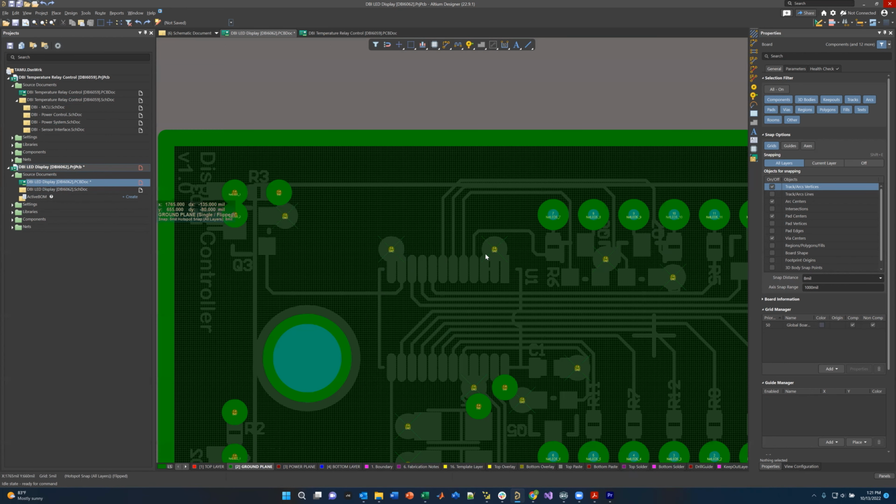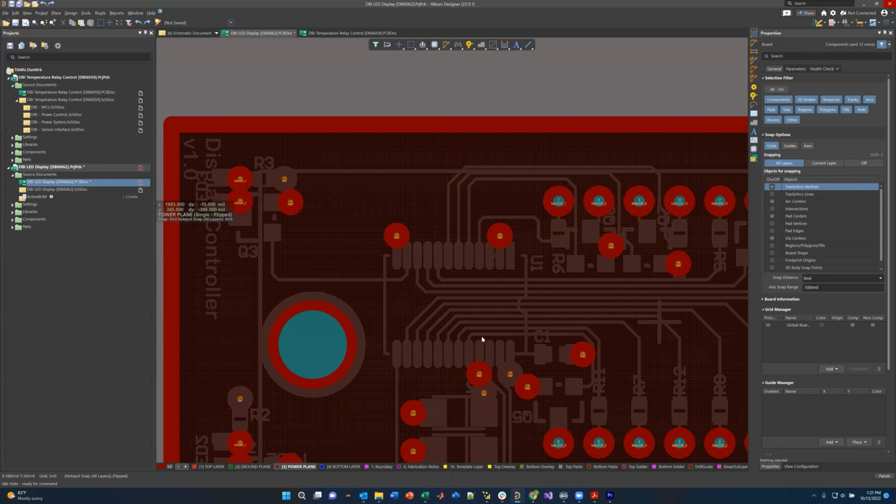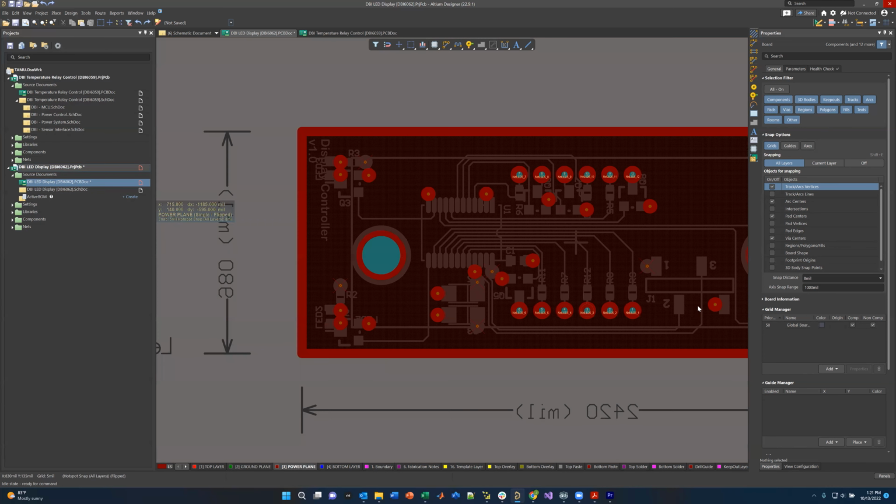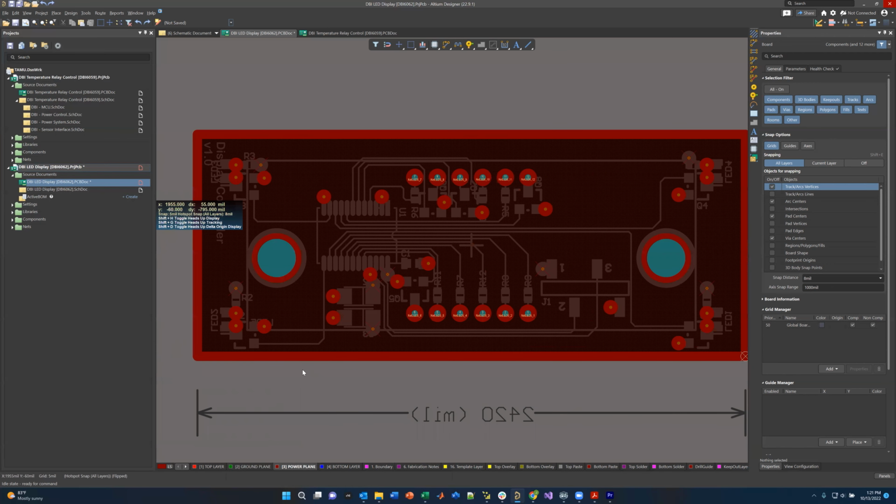That's ground. You notice all the grounds look like that. If we go to power, which in our case is 5 volts, the 5-volt layer does that for its vias, and of course everything else is isolated. When they build the stack of this board, they will have 4 separate sheets of copper, basically, and then they glue it together, mate it, and drill it, and it's all put together. So the process to build a circuit board is fairly sophisticated.